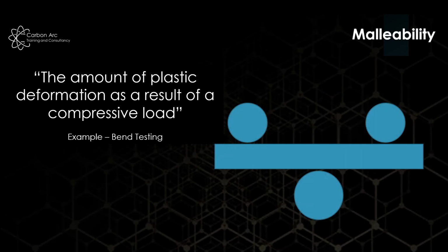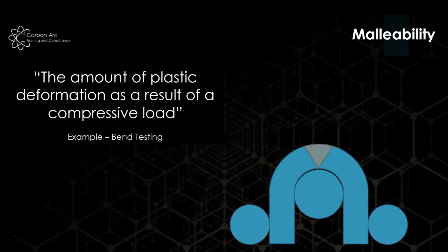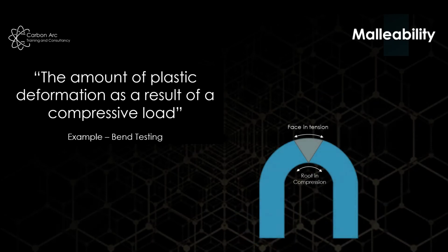So here's a very simple 3-point bend setup. Our former size here is normally around 4T, so the diameter of our former is 4 times the thickness of the material we're going to bend. What we do is we push them down and form our material around. In this case, we have our face in tension and our root in compression.